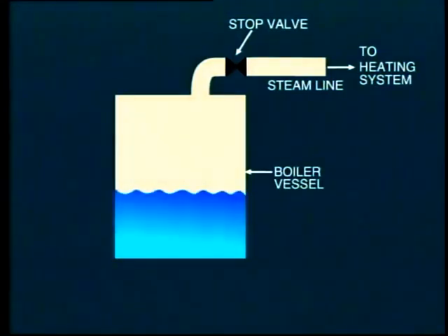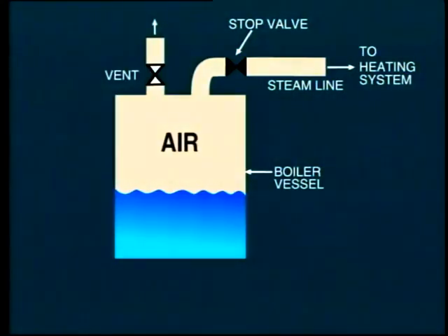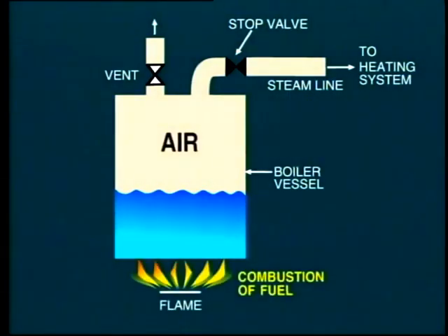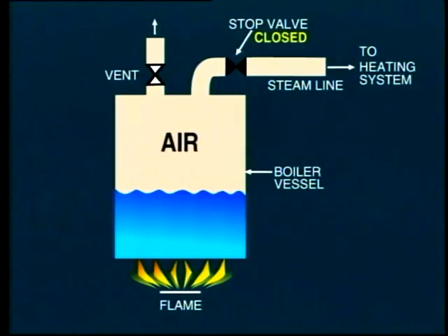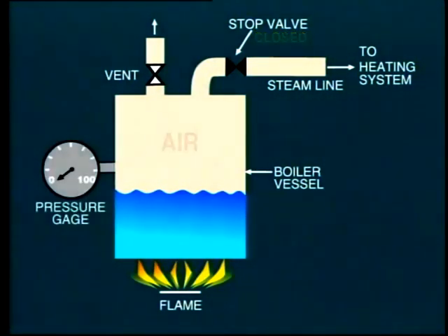The vessel must be filled with water to approximately the halfway point. Before startup, air fills the space above the water as the air vent valves are open to atmosphere. It is clearly necessary to provide heat, and for this hypothetical boiler, we will provide this by combustion of fuel below the vessel. Initially, the boiler is fired with the stop valve closed. This is to allow pressure to build up within the boiler. Initially, it takes some time for the temperature of the water to rise from ambient to the boiling point.